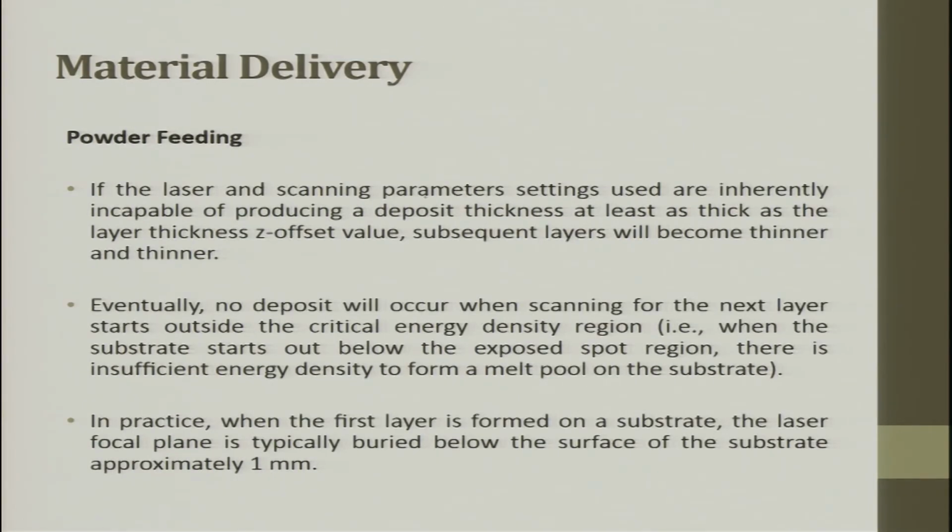If the laser and the scanning parameter settings used are inherently incapable of producing a deposit thickness at least as thick as the layer thickness Z offset value, subsequent layers will become thinner and thinner.